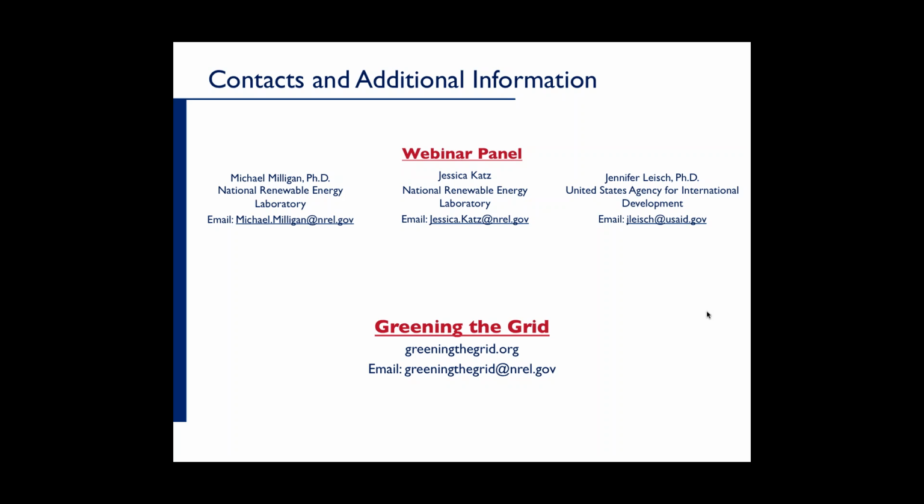Okay, I'll repeat the question because I'm not sure if anybody heard me. The question was, explain more about why we do not need any storage when we have 30% energy from wind and solar. The answer to that question is because we typically have generation on the system that can be controlled or even turned off. And so during periods of high wind or high solar, we can turn down a gas unit, or we can turn down a coal unit, as you saw in some of the graphs, and that sort of makes room, if you will, for the wind or the solar energy.